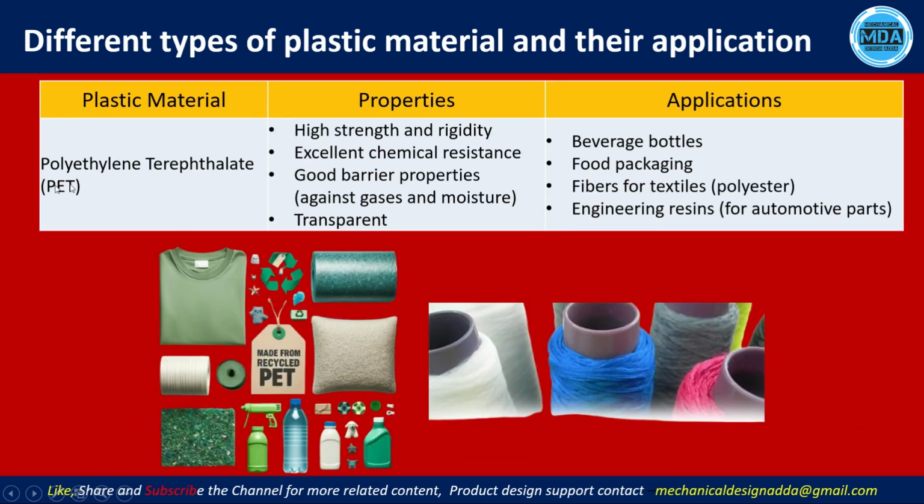Next is polyethylene terephthalate, generally written as PET. It has high strength and rigidity, excellent chemical resistance, and good barrier property. And with PET, we can produce transparent products as well. You can see over here the different applications of PET.